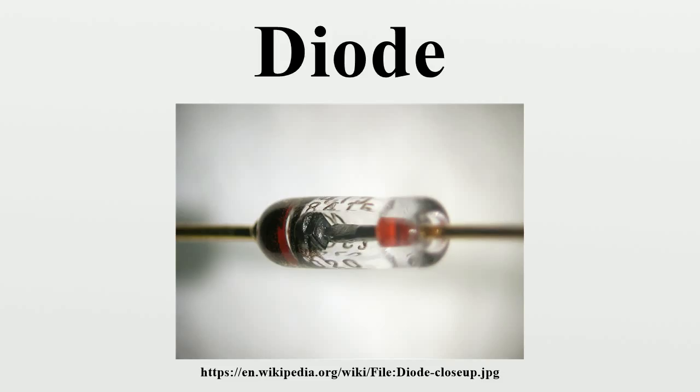In addition, most receiving sets had vacuum tubes for amplification that could easily have the thermionic diodes included in the tube, and vacuum tube rectifiers and gas-filled rectifiers were capable of handling some high-voltage, high-current rectification tasks better than the semiconductor diodes which were available at that time.